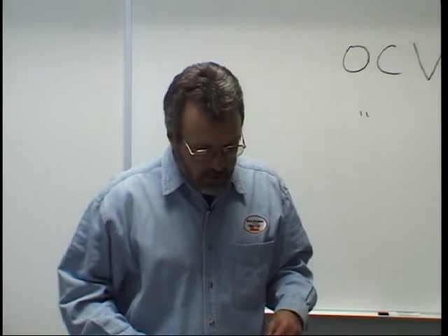Number one reason you have to match the mechanical properties of the base metal with whatever type of filler metal you're using. Number one reason. Highlight the first part of the second paragraph. There's a bullet coming out of here.